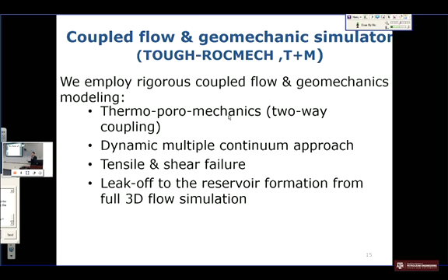If the friction angle is the same as the dilation angle, then there will be an associative flow rule. If those are different, then we have a non-associative flow rule. Yes. We have to investigate the numerical characteristics for the non-associative or associative flow rule models. Volumetric change is pointing in one direction based on the Mohr-Coulomb surface.